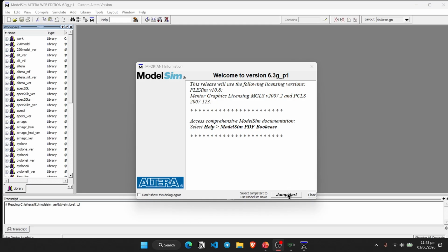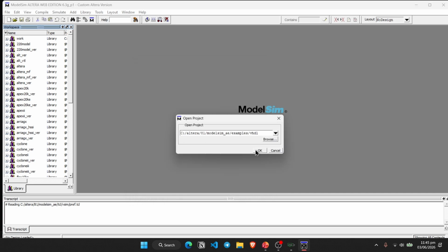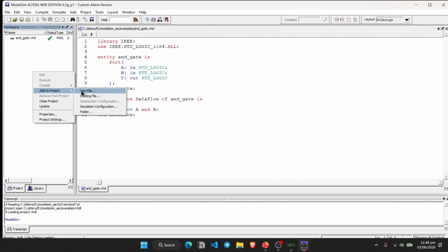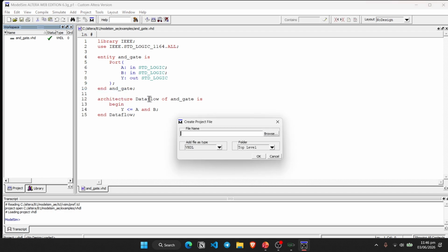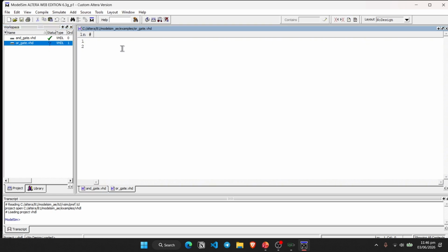So we have opened our ModelSim and we will click on Jumpstart here. And we will open a project. Since in the last video we have already created a project, we will open it right here. So we will click on OK and our project will be opened. We will double click here, or we will right click and add to project, new file. So I will write OR gate and click on OK. So OR gate will be added to our project. We will double click it and this will be our code writing window. So we will write the code of OR gate here.